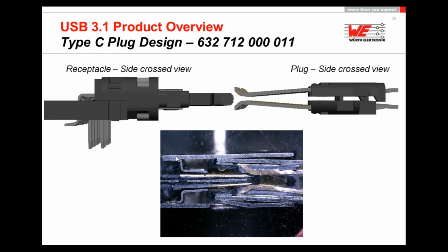So we have to analyze the whole system. Here we see a picture of the cross-section view of the receptacle and the plug, how they are fitting together. And like we can see here in the real cross-section picture, we have a massive construction design of this type of connector. So first we have the end lock, the blocking system so that you can't slide the contact deeper in, and that's important to define really the length of the signals, because when we imagine the mating part would stay in like we see it here in that picture, it's a completely different signal wavelength compared to when you slide it in until the end.